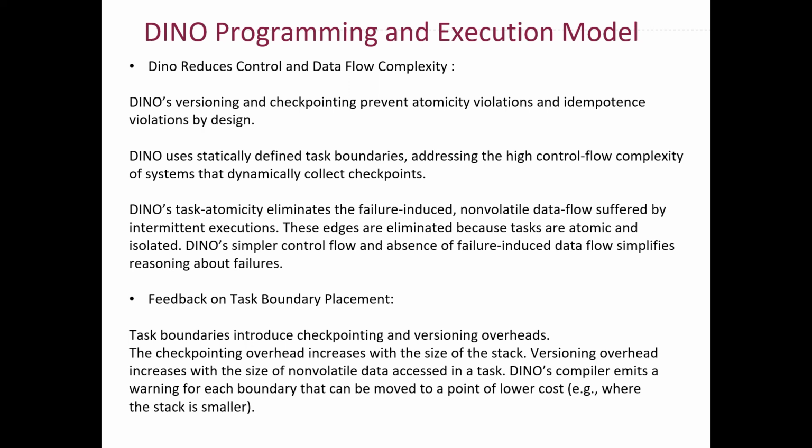And then again, the second cost dimension is that failures of actions such as IO actions may be expensive to repair. So making such tasks very short and minimizing unrelated actions minimizes this risk. So Dino's compiler emits a warning when a task includes access to a peripheral register, indicating likely non-idempotent hardware use.